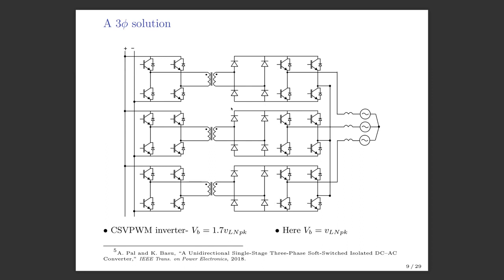So you can actually connect three such single phase units and intelligently connect the output, like we are making one output and making a neutral, and the others we are connecting to this three-phase grid. We can still generate the three-phase AC by modulating these three H bridges. Remember, now the modulation or the pulse width modulation is happening here in these bridges. So this bridge will modulate and give you phase A voltage. This will give you phase B voltage, and this will give you phase C voltage.